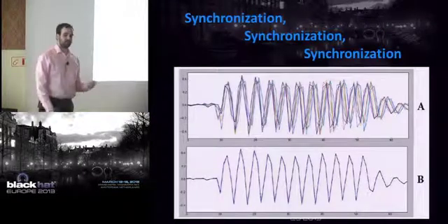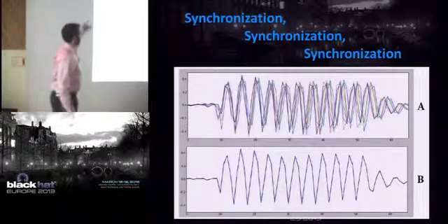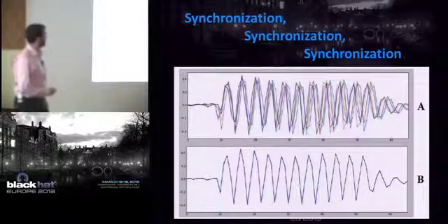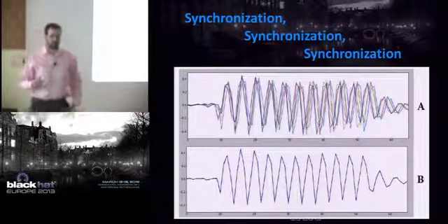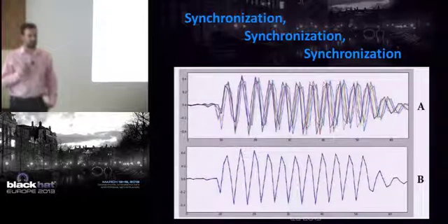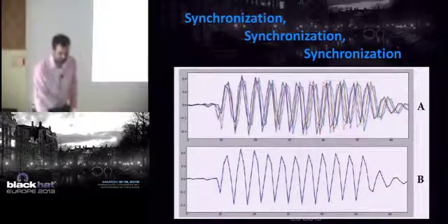And where this comes from, the core part of this, is the requirement to synchronize your power traces. These two graphs: the top one is sampling at 100 megasamples per second. This is sampling a hardware AES system that basically doesn't work below about 250 megasamples per second. You need that minimum speed of the scope.